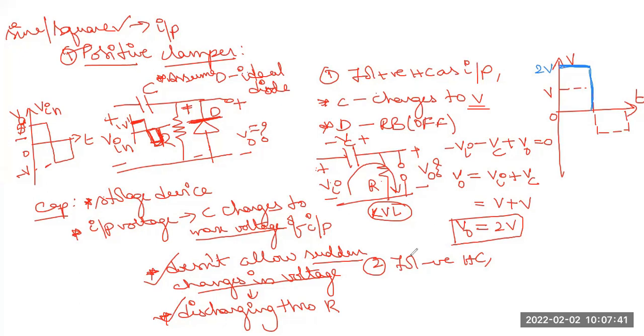Okay. So what is that you write here? For the negative half cycle as input, we see that the capacitor starts discharging. And also, what is the state of diode D? On state. It is on state because it is receiving negative here, positive here now. So your diode is forward biased. So it is in on state. So what is the equivalent circuit at this instant?